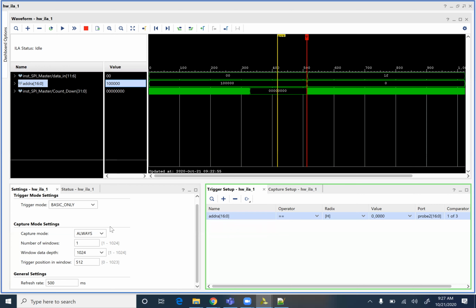I basically remember something with the speed it has, but yeah, I don't think you have to set it to Z. I think it will be okay, but we'll check it, because this is new for me. I'm pretty sure I said this last time, I almost never use I2C because of the added complexity. SPI is faster and simpler. It just costs wires, which can be a design decision that really does limit you, but I try to avoid it.